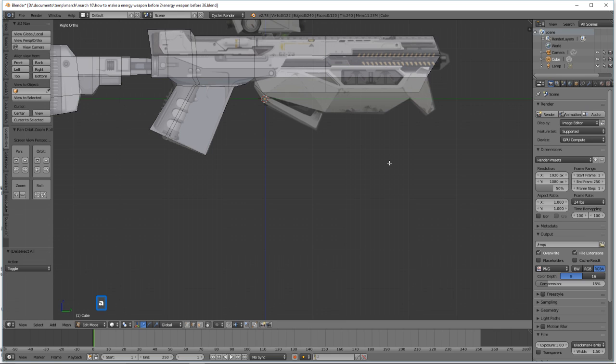And I'm going to press A to deselect. I'm going to hover my mouse here, hold control, and then while holding control, I'm going to press R. Then I'm going to left click once. Because I left click once, I can move this loop cut. I'm going to move this here. Okay, about there. Looks good. I'm going to left click a second time to lock that in. I prefer for this to be straight, so I'm going to press S to scale on the Y axis 0. And then left click to lock that scale in.